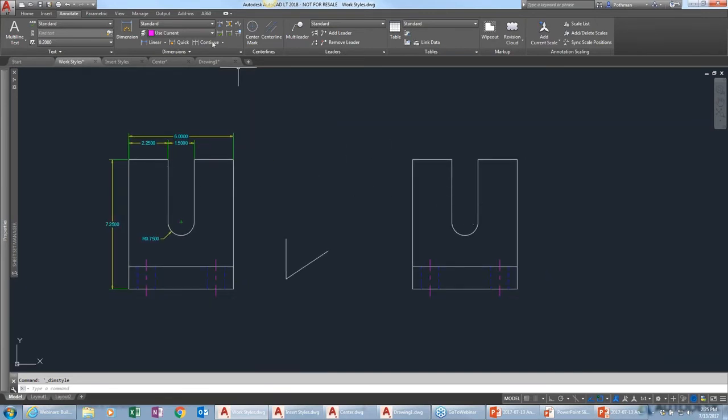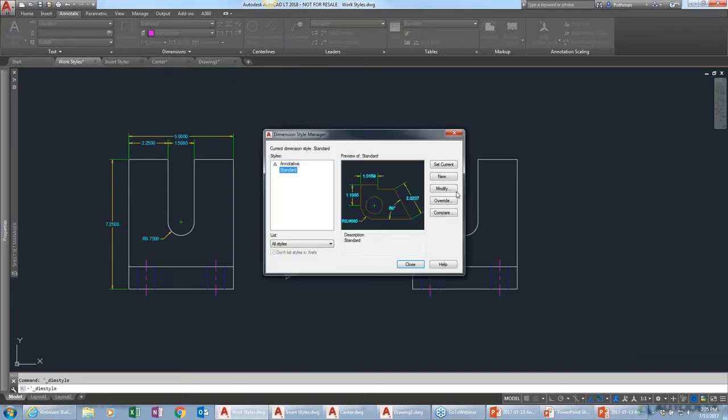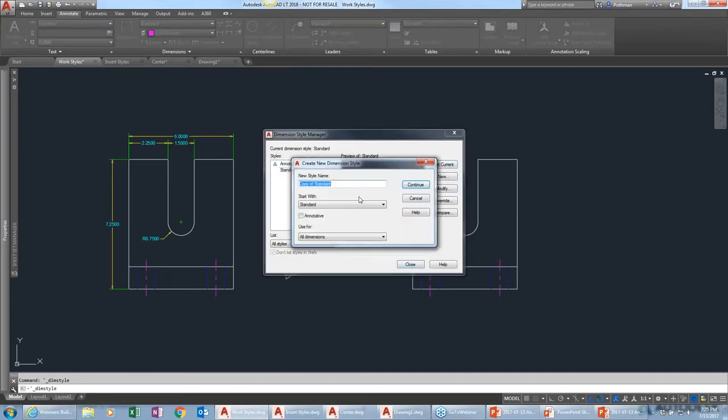But let me go back to my dimension styles, and I'm going to create a new one this time, and I'll type Acme as opposed to AMCE like Mariah does. So this is going to be Acme-dims, and just adding something like dims or notes or leader or title block or whatever into your styles will help with remembering kind of what's going on with it.